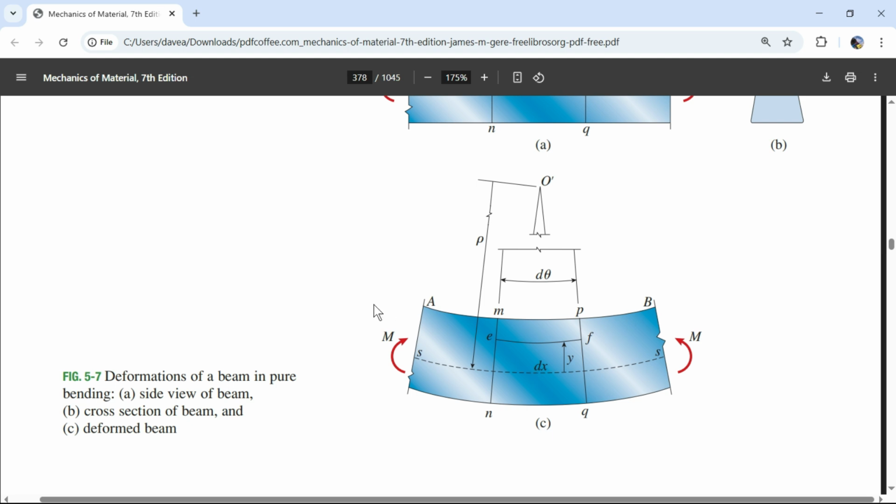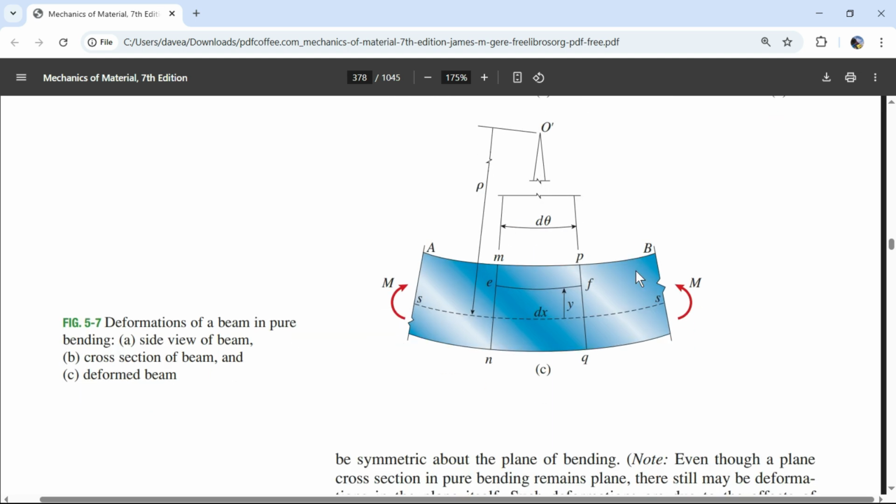No one does, because you can't see it. Usually the changes in length are just small and you're not going to notice it. It's worse because, let's say you're torquing a bolt. You can easily over torque it and then you're into plastically deforming it, and sure, you lengthened it. Up to the point where you're getting that max pressure that you can put in things, that change in length is very small and imperceptible when it comes to most building materials, steel, wood, concrete. And so that's just a bummer.